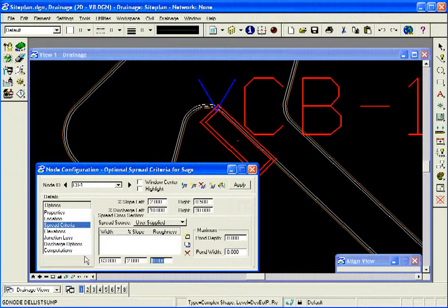and then a spread source, or a Manning's number for the roughness, 0.012, and I add that using the icons on the right hand side of this list. I add it to the list. In this portion of the parking lot, I simply have a raised curb, so there is no gutter, so it's straight 63 feet away to the other edge of the parking lot, or parking bay.